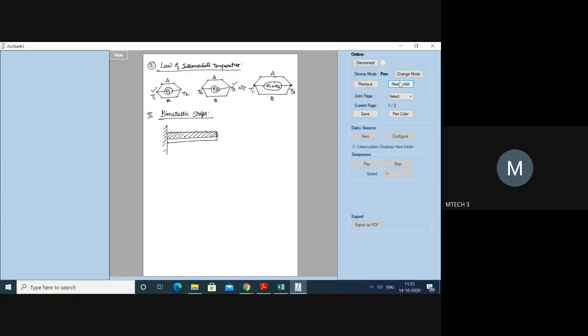Now we have two different metals which are clubbed together. We have two strips of metal. Please understand, bimetallic strip. Simple. Bimetallic. There must be two different metals. Bimetallic strips are another way of measuring temperature. So two different strips of metals are fused together at this point to form a rigid single structure. If you observe, these are not two different structures. This is a single structure.